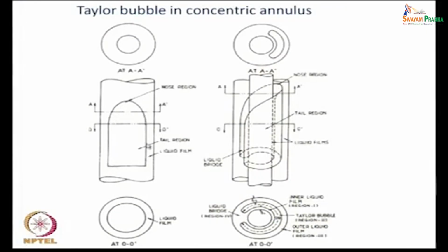But very interestingly, we found that in this particular case, the bubble was distinctly asymmetric. Why did it become distinctly asymmetric? Because we found that when we insert a rod, the bubble which was rising tends to wrap the rod, isn't it? But it does not wrap the rod fully, it wraps the rod only partially, and therefore, it gives a kidney bean shaped appearance which is evident here. Had it wrapped the rod completely, then we would have got an axisymmetric, nice rotationally symmetric bubble.